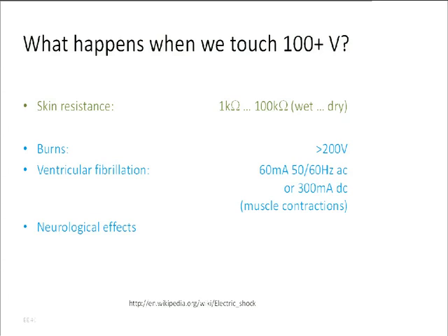If I have enough current, enough voltage, enough power and energy, well then, it's like a cooktop, right? So that's not good. Usually that takes quite high voltage, quite a bit more than 100 volts, several hundred volts for that to happen. You cannot burn yourself with just 10 or 20 volts, the battery voltages or so.